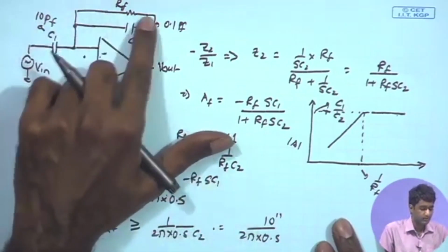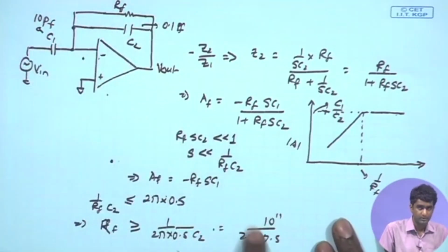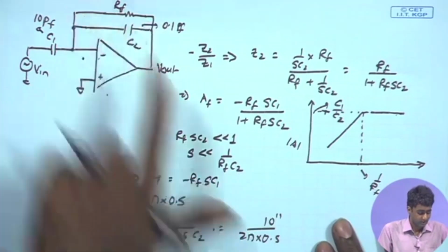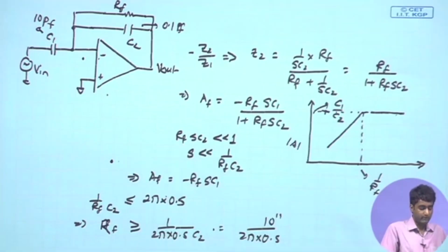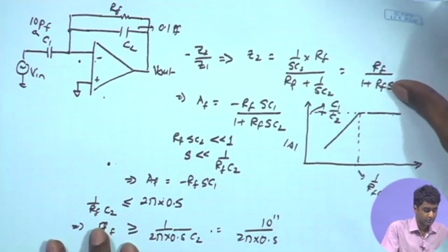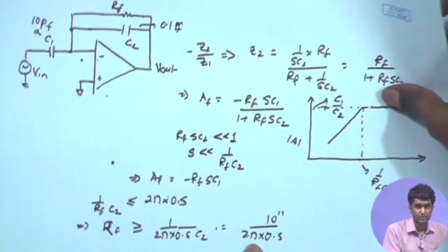So we are looking at the equivalent noise current contribution. If you are using such subthreshold regime transistors to implement such an R_F, the overall noise current will also be small because of the 1 upon R dependence of the noise current. Now let us look at the transistor level implementation of R_F and try to see what non-idealities we may need to address. Any question before we proceed towards transistor level implementation?